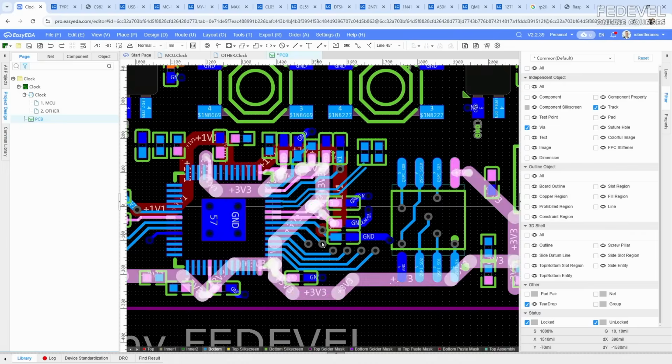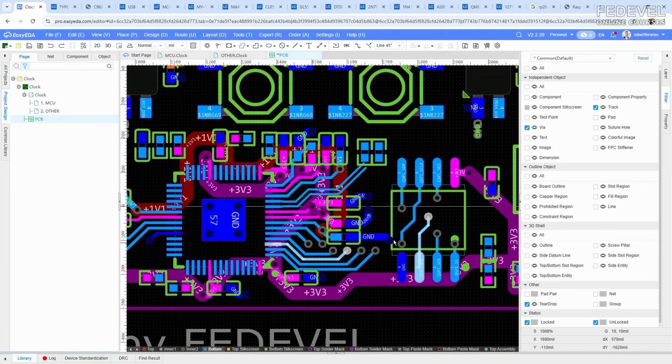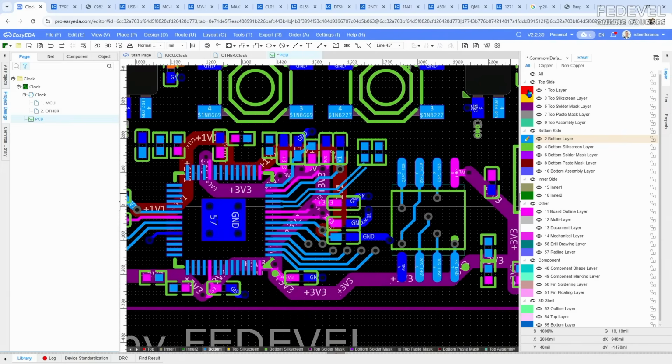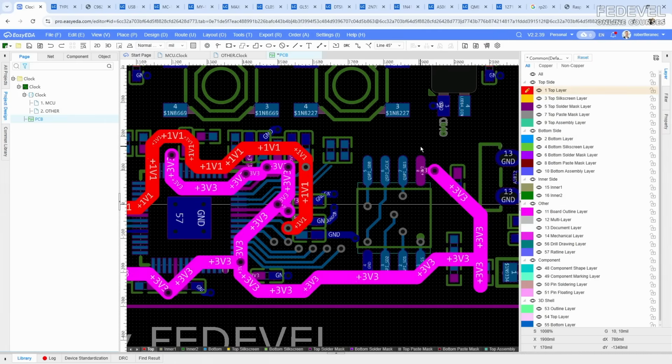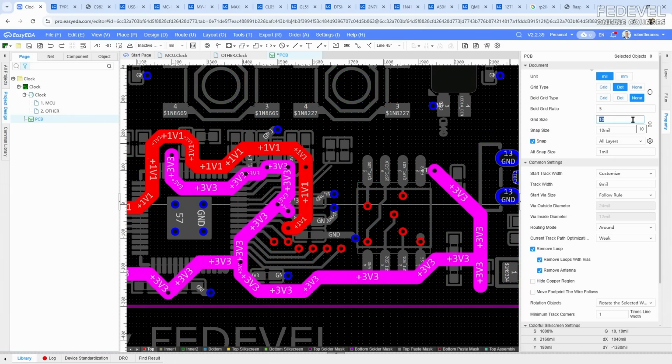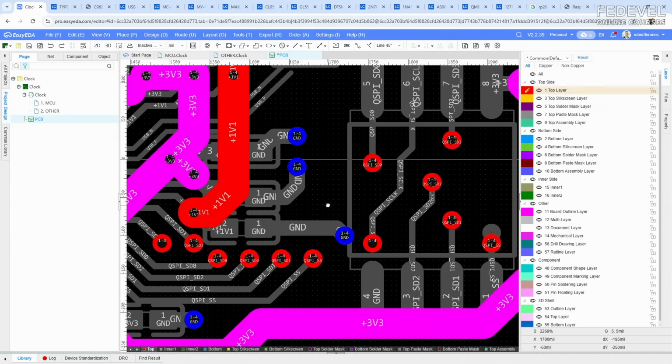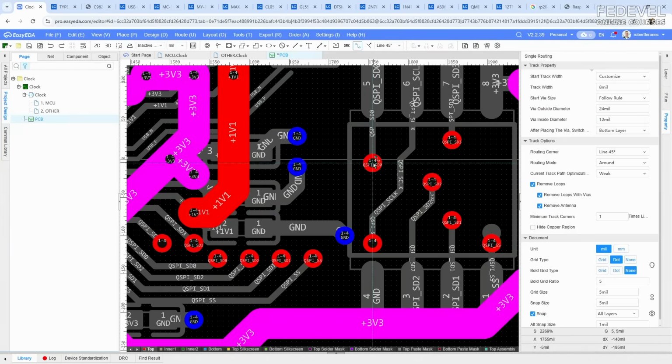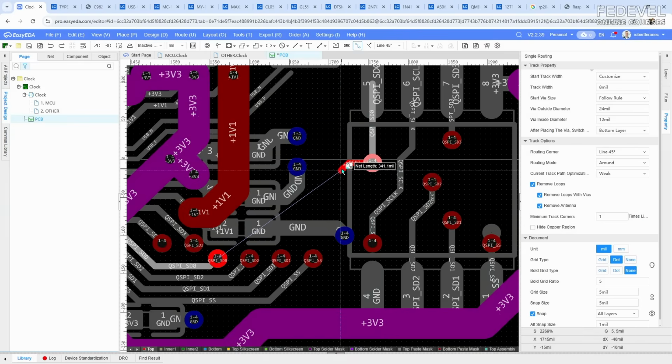Now this flash, we are going to connect it on top layer and press Shift S. You can change the view. So you try Shift S and you will see now this second layer is grayed out. But if you do it Shift S again, then it will completely disappear and only one of the layers will be visible. And then press Shift S again, you will see all the layers.